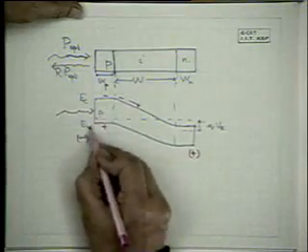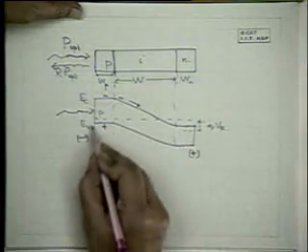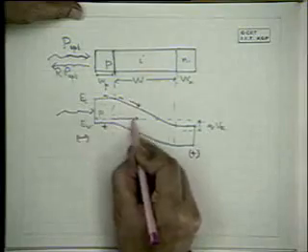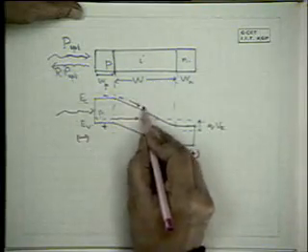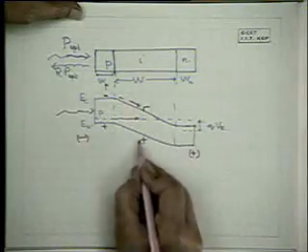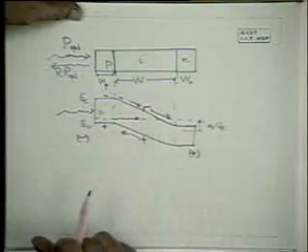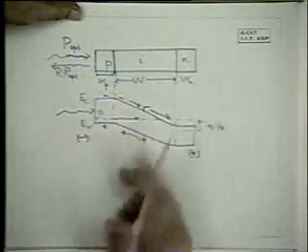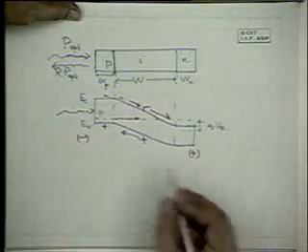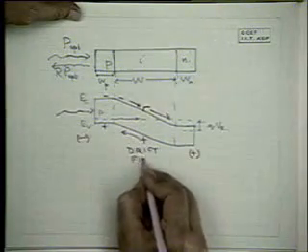This is a small region, few thousand angstroms. This is again a small region, so quite a lot of the light will enter into the I region where electron hole pairs are created, and this is the main absorbing region where electrons and holes are separated due to this built-in electric field. And due to this negative bias, this is a depleted region. Okay, so this is a region where there is a drift field present.